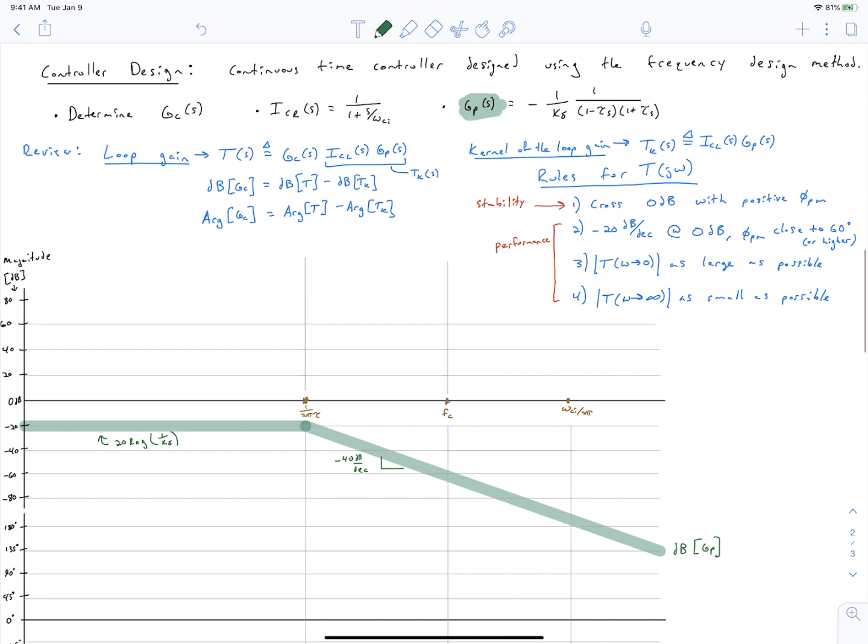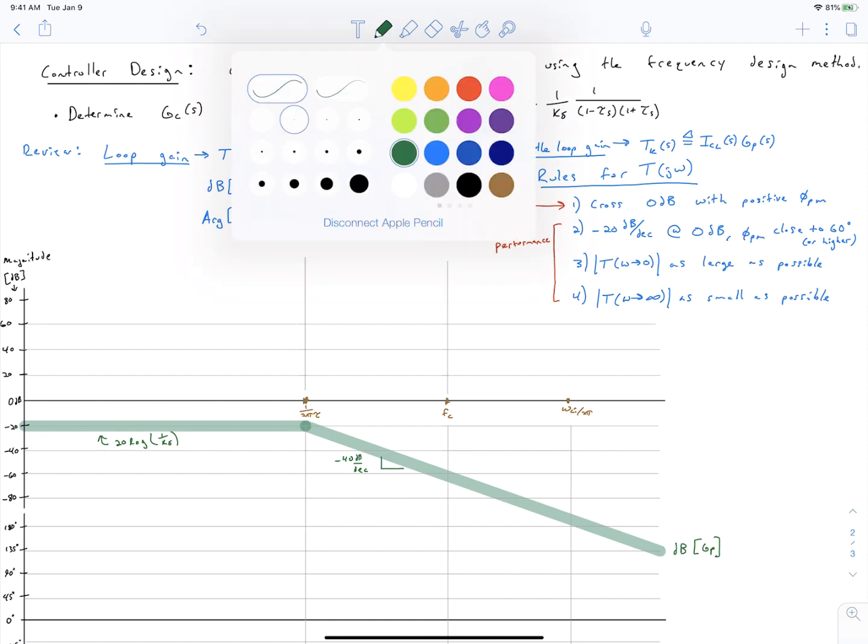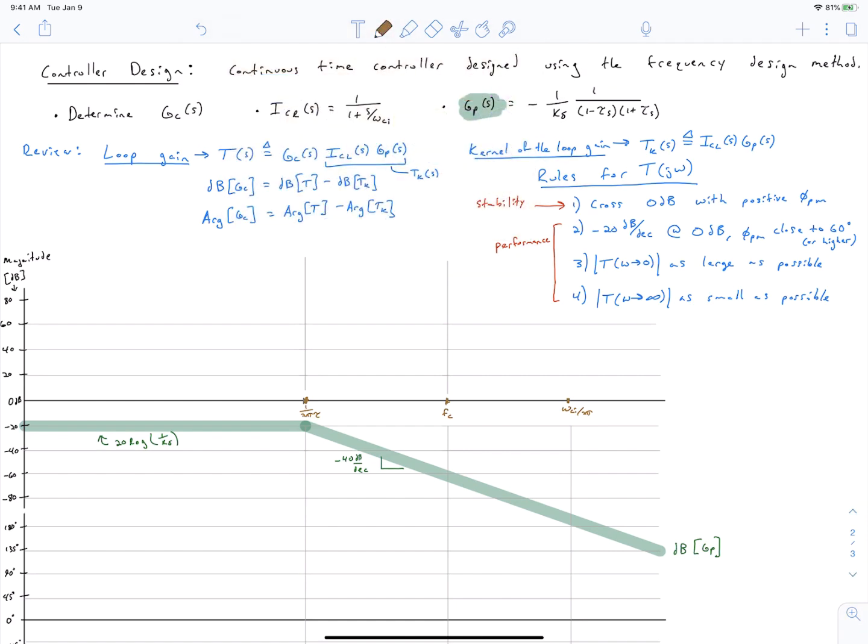Okay, next we're going to plot the Bode plot of our current regulator. And I'm going to assume in this Bode plot that this pole out here is at a pretty high frequency. You see I've labeled it on here. And remember that this is a logarithmic plot where our x-axis is in hertz, and then our y-axis is in decibels for magnitude and degrees for the phase angle.